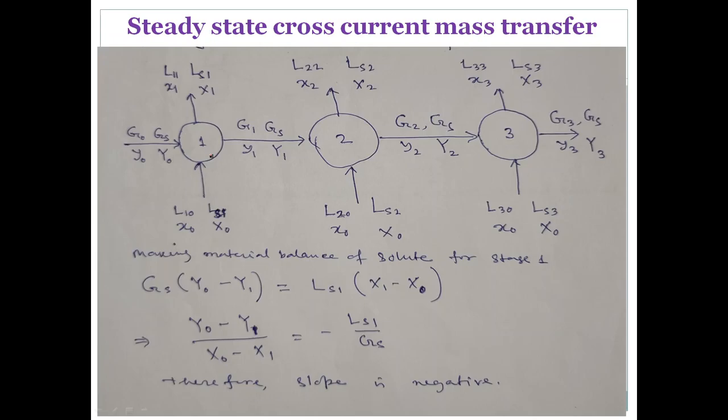And that BTX will move from the petrol phase to N-methyl pyrrolidone. Okay. So mixer and settler. If the top phase is, let's take, petrol, the bottom phase is N-methyl pyrrolidone. So at this point I can separate this. Okay. So mixer and separator, this combination is generally called one unit.